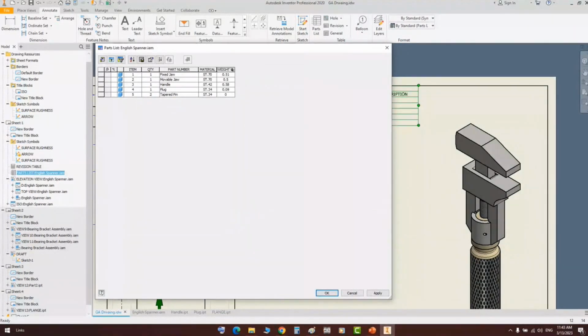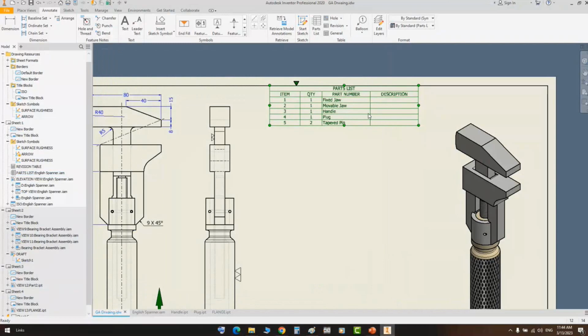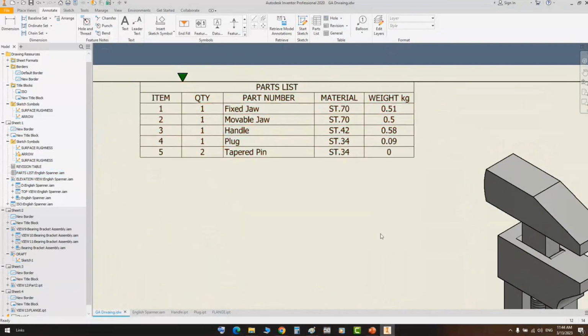Okay, so you can figure that it will appear on the top view. You can change the width, let's make it 30. No problem. And when you click on OK, now you can change this part list. So by that way, you can include other columns in your table. So how to make your own bill of material list, which includes as a default the required fields.